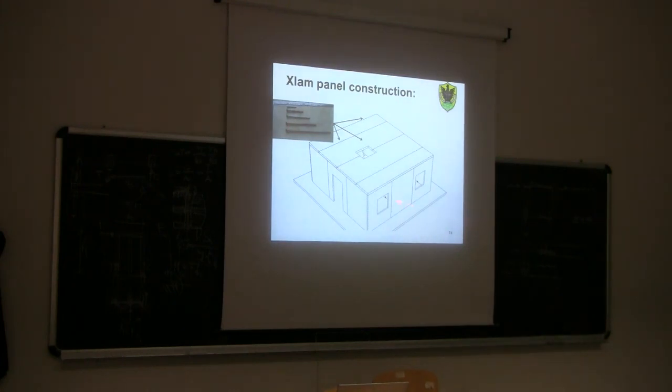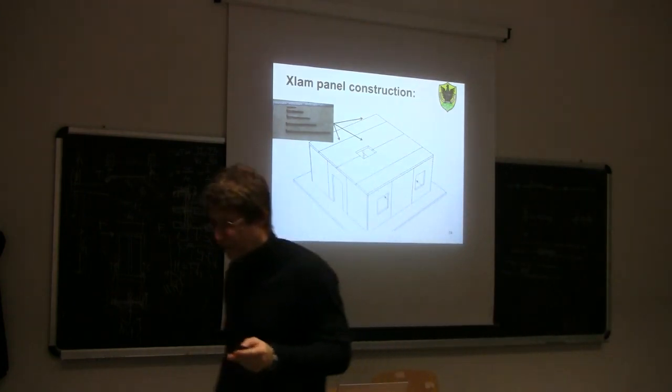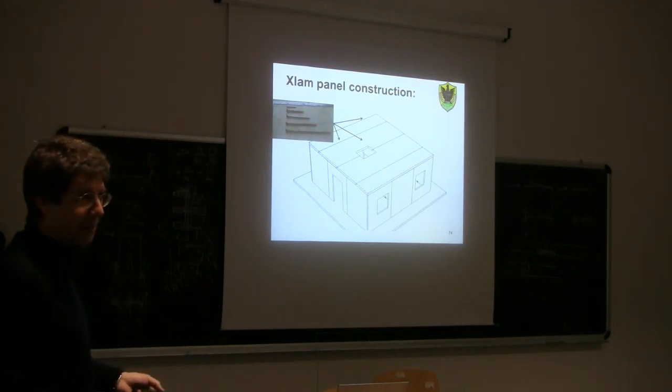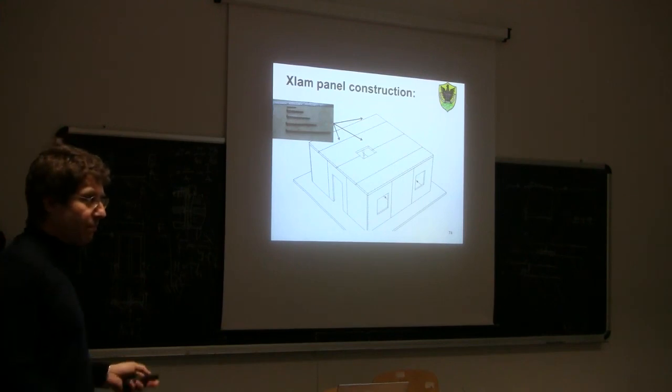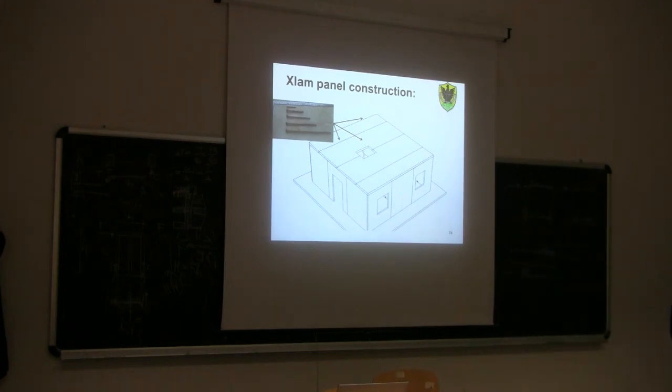So the panels are connected to each other using these screws, and then they are connected with some other screws to the vertical wall, inner and outer wall. So this, as you can see, is like a box. It's a real box, so it's extremely strong. The structure here is very, very strong. Just a reminder, of course, that in this box, the weakest link is the connection. Usually it's very hard to break one of those panels. Usually, what breaks first is the connection. So the connections are the weakest link in this kind of box structure.